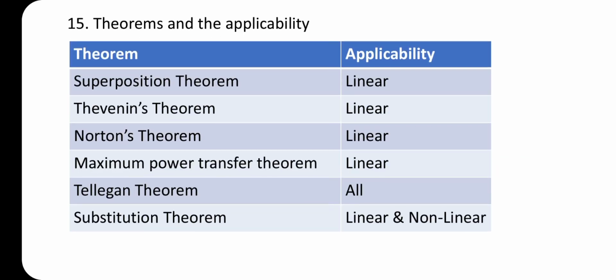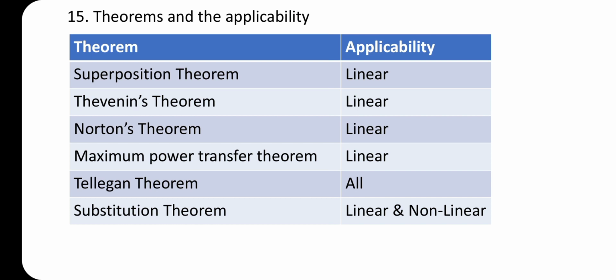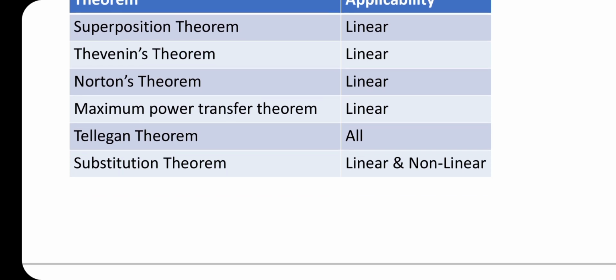Theorems and applicability. Superposition theorem, Thevenin theorem, Norton's theorem, maximum power transfer theorem can be applicable only in the linear circuits. Tellegen's theorem can be applicable in all circuits. Substitution theorem can be applicable in linear and non-linear circuits.